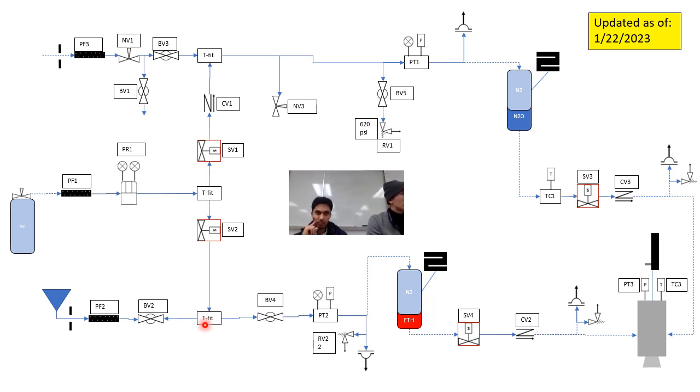Okay, so you show up, you keep your ethanol and nitrous oxide far away, and you do a few things in your pre-fill process. So again, one more high level thing. I'm going to go through the pre-fill process, the fill process, which consists of filling the nitrogen, followed by filling the ethanol, followed by filling the nitrous oxide, and then the pre-test process, and then the hot fire process. Almost all of that effort goes into the filling process. And it goes in order of least dangerous to most dangerous.